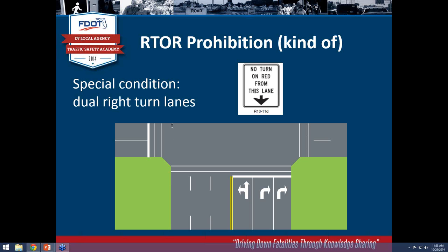So I would tend to make it protected, mainly to protect the pedestrians. There's a question about flashing mode. Someone would like a little bit more discussion about some of the safety concerns with having signals flash at night. Yeah, the nighttime flash really was something that was popular back in the 70s and early 80s, when there was a whole lot of concern about energy prices and just saving energy. At that time, each indication was a 135-watt bulb, so you're burning lots and lots of electricity running those things at night when you don't have much traffic.